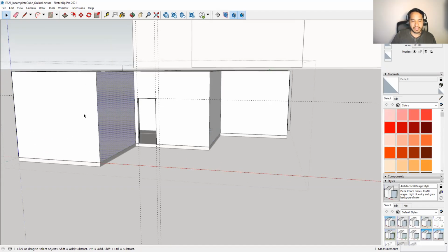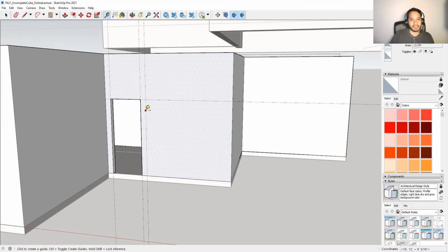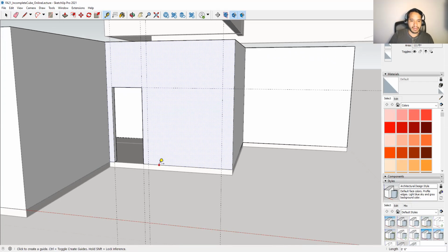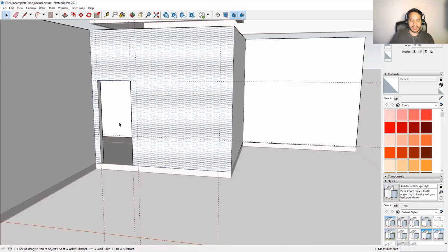That's the reason why I'm able to edit these walls. So I'll use the tape measure and go out, let's say, 7 feet, enter. And maybe the height is something rather low, so we'll go 30 inches. Now I have the boxing of my window.